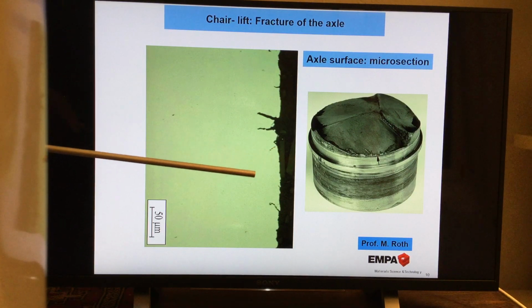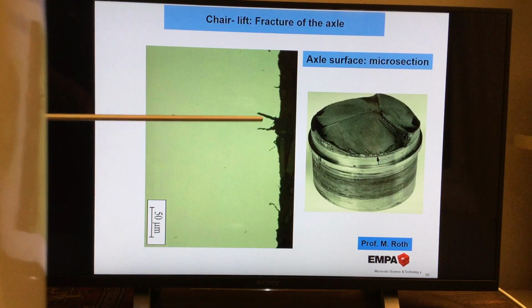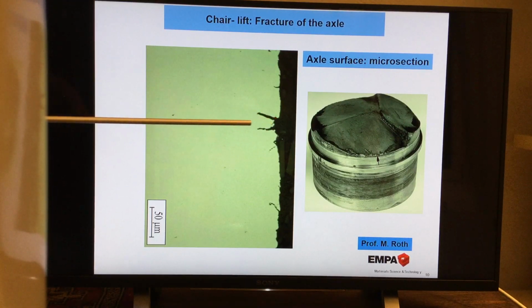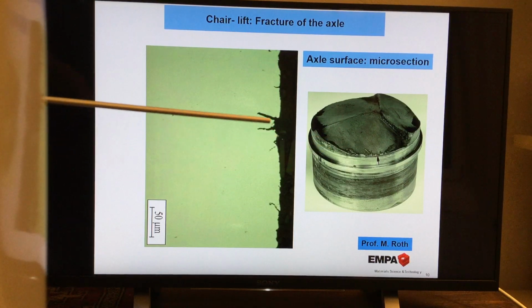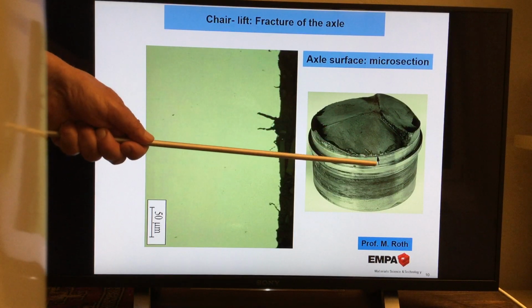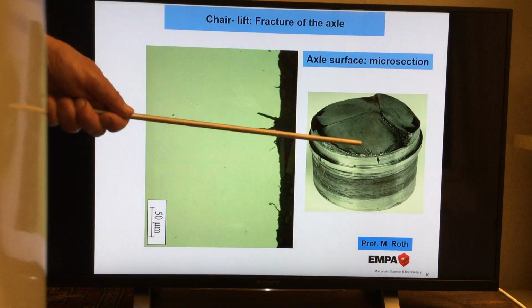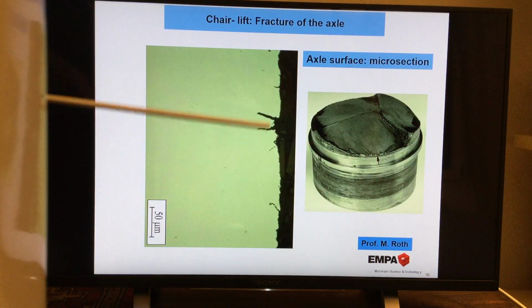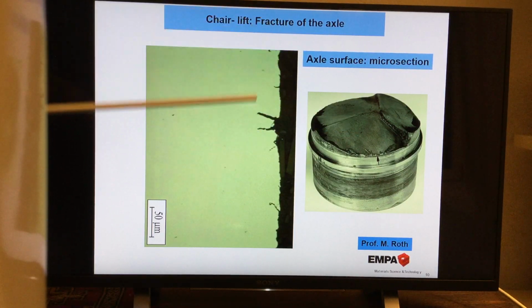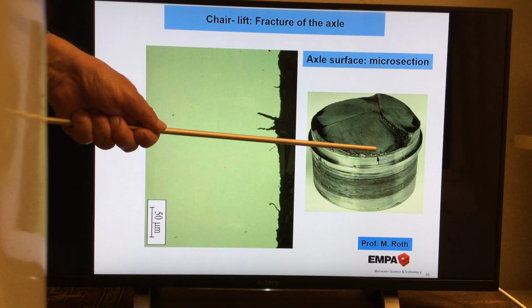And more important, at the ground of this corrosion pit, cracks started growing inside the material. So that's the initial state. Of course, these cracks underneath here, by the time, lose the power to grow, because the main stress and the main crack was going here and then they stopped. But obviously that is very clear, this kind of mechanism was the main starting point for that crack here.